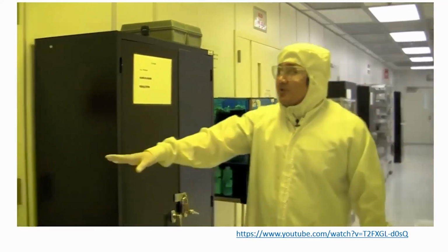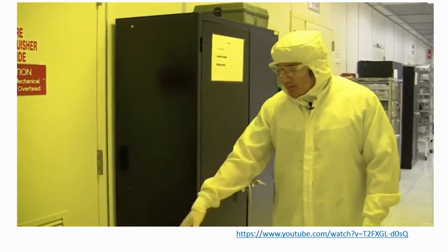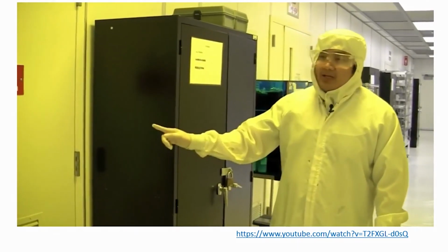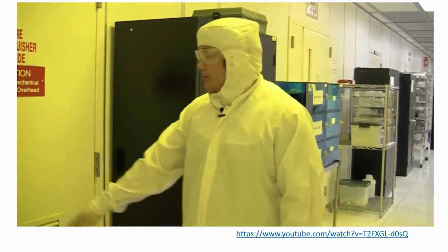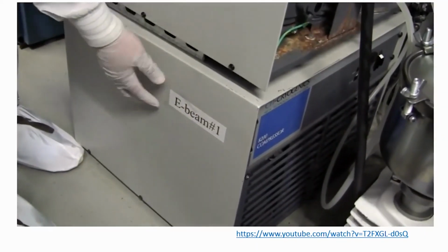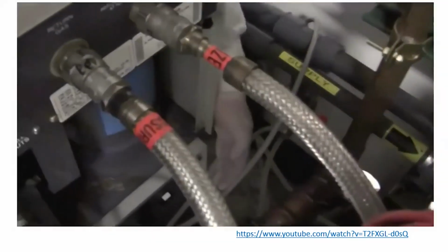The compressor is found in this chase, room 2337. And before you go in, you want to make sure there's no odors or chemical spills. If there is, then you will notify staff. But it looks like it's fine to go in. So we're going to go in and turn off the compressor. This is the compressor for the E-beam 1 cryo pump. So it's labeled E-beam 1. It's the bottom one. And if the cryo pump is dumped, you need to turn the switch off. The switch is located here, and you would turn this off if the cryo pump is dumped. After it's turned off, you notify staff and let them know that the system has been dumped.